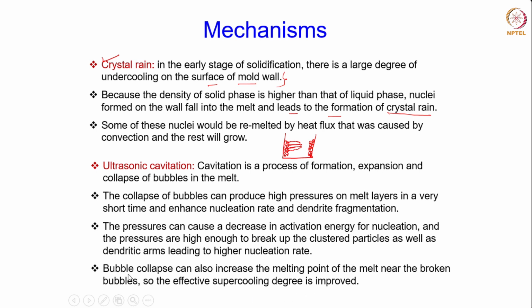And bubble collapse can also increase the melting point of the melt near the broken bubbles, and therefore the effective supercooling degree is also improved.